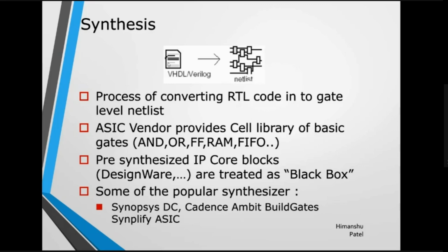They need to know that they have used this library model for the AND gate, this library model for the flip flop. So they need the gate level netlist synthesized with the proper library. That process is called synthesis, and this synthesis is done by EDA tools.